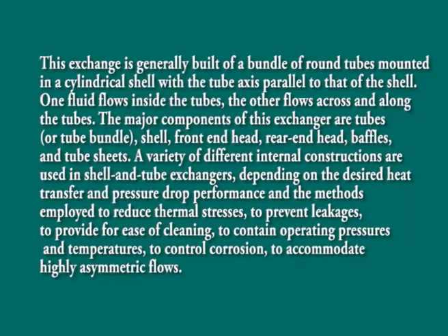the figure. Seeing the shell and tube exchangers, this exchanger is generally built of a bundle of round tubes mounted in a cylindrical shell with the tube axis parallel to the shell. One fluid flows inside the tubes, the other flows across and along the tubes.